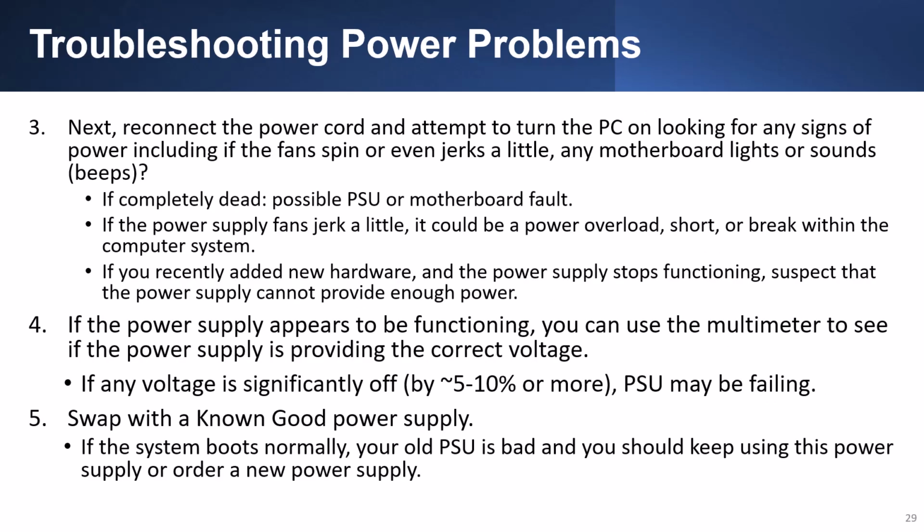Next, reconnect the power cord and attempt to turn the PC on, looking for any signs of power, including if the fan spins or even jerks a little, any motherboard lights or sounds or beeps. If it is completely dead, suspect a possible power supply unit or motherboard fault.